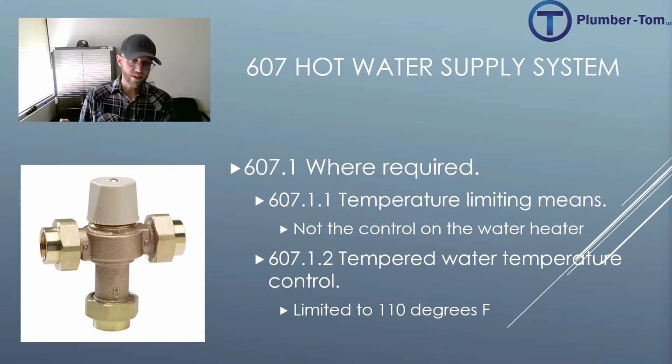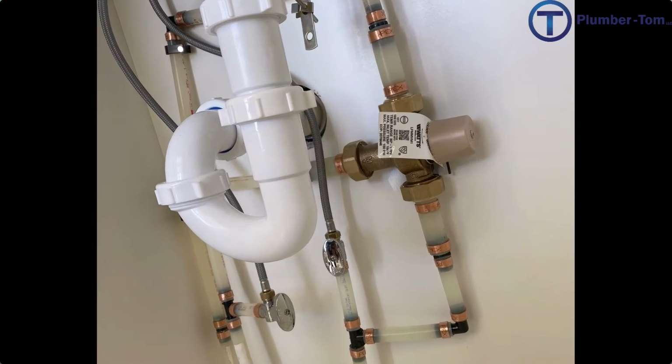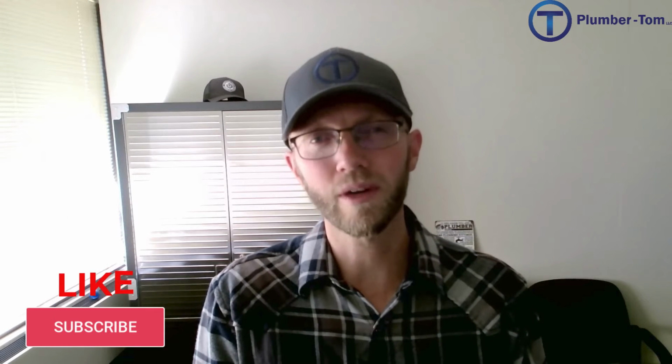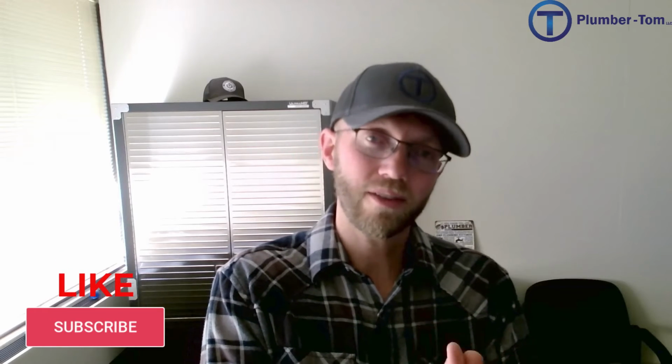607.1.1 talks about temperature limiting mains. This is where we use a valve to restrict the heat of the water, a mixing valve, for example. And it states that if we're going to have a limit to the temperature of the hot water, we cannot rely on the water heater itself to limit the temperature of the water. Why not? Well, you can set a tank type water heater to a certain temperature, but does that mean that's what it's going to deliver? It can fluctuate. So we can't rely on that. And therefore we have to have some way of mixing it down in a way that we can control that.